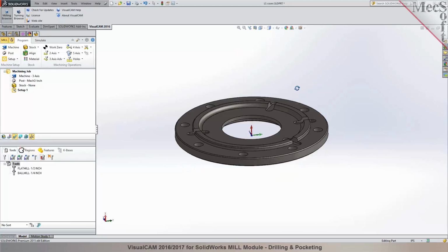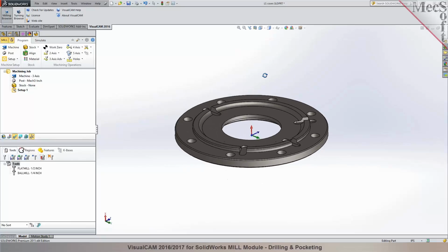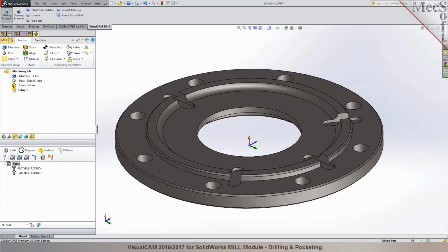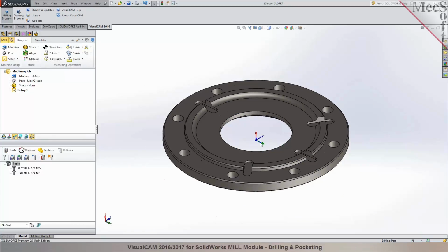And by looking at this part, it looks like your Z-axis is not oriented from the orientation you're probably intending to mill this part from. Is that correct? So you would like to set the Z-axis to be normal to the space. Is that right? Yeah, you can do that. Okay. So currently your Z-axis is basically in the same orientation as how you have it established in SolidWorks. So the coordinate system for machining is by default in the same orientation as you have it defined in SolidWorks.